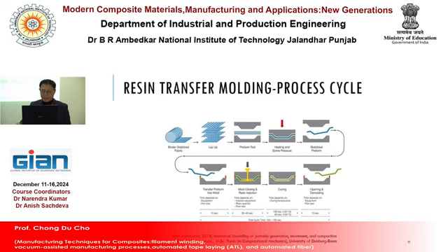Mold closing and resin injection takes 30 to 40 seconds. Curing is 120 seconds at 120 degrees, and after that 90 seconds at 130 degrees is needed.